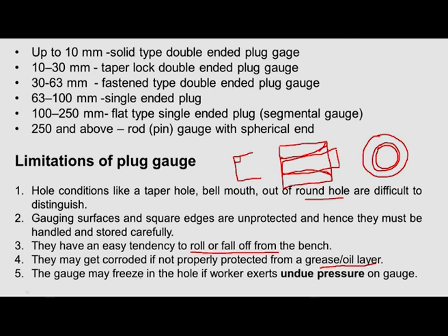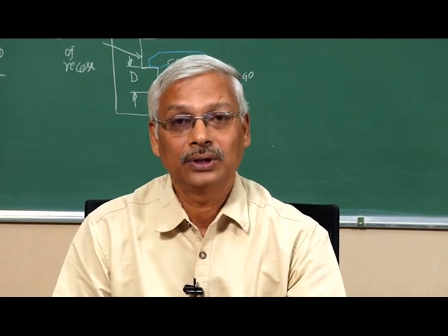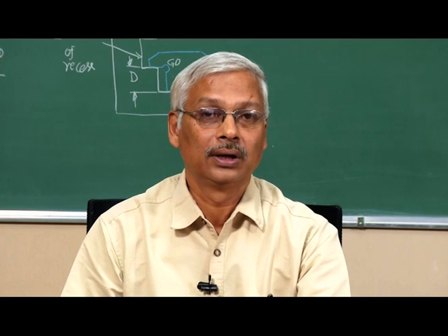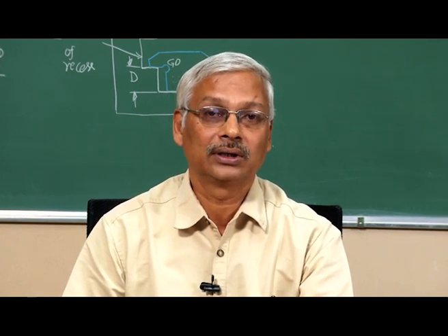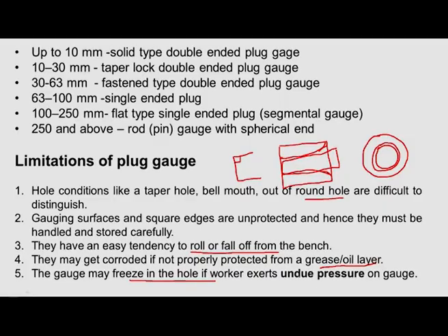And then the gauge may freeze in the hole if the worker exerts undue pressure on the gauge. This is very important. We should not force the gauges into the hole. What happens if we force the gauge into the hole, it will enter but it will deform the hole, the hole may expand. So undue pressure should not be exerted.